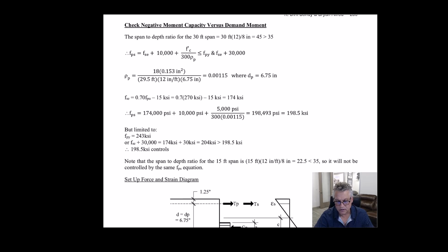And what's really strange is when that'll show up is when you're doing a design and you're using one of the real cool hip finite element programs that actually does the rebar for you and even draws it, and you look at the plans and you see reinforcement when you're looking at the flexurally required strength reinforcement, and you see it on one side from the center line of the column towards the longer span, but you see no bonded rebar in the other direction. So you have bonded reinforcement that's stopping right at the midpoint of the column. And that's actually what the program is doing, is it switched FPS equations.